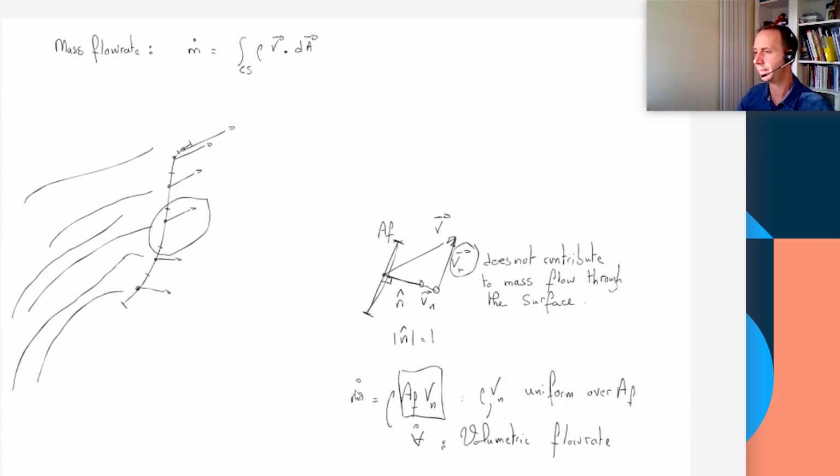If you multiply by density, which is rho, then you get the mass flow rate. And we assume everything was constant. So clearly it is not constant here, there is a curvature. But in the limit, when you make that area very small, you will end up with all these constant or small enough to neglect the variations. And that transition from large to small enough comes from essentially the difference between discrete notation and integral notation.